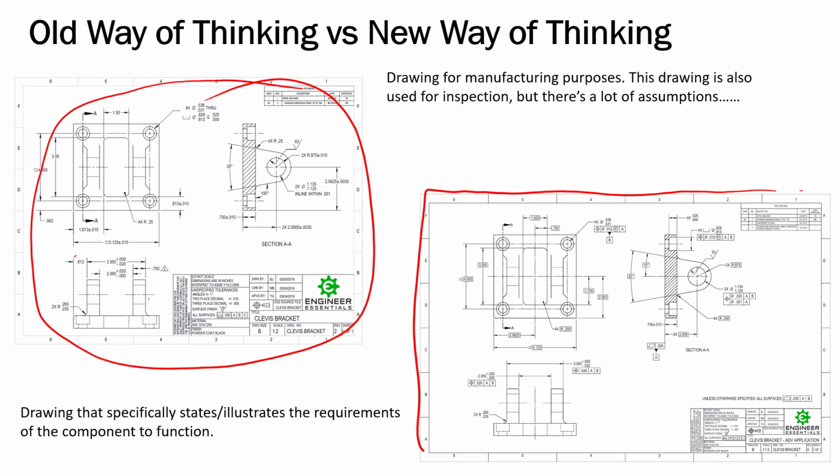See if they are willing to get training on GD&T, or maybe what you're sending to them is so small that, if you know the part's going to go to them, maybe you never put GD&T on it. Or you put GD&T on it and, like I said, you work with them specifically on how to inspect the actual part, because they don't need to know the manufacturing part of it. They need to know their limitations, and when it comes down to inspection, what's really critical and what kind of approach they should take at inspecting those parts.